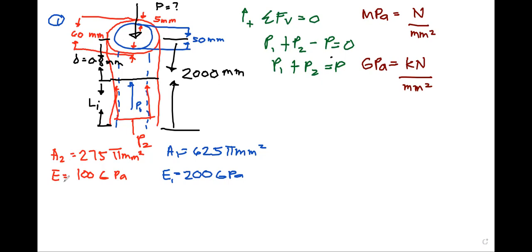So, we can say that deformation 1 is equal to deformation 2. And of course, if their deformations are equal, length 1 and length 2 should also be equal. Okay? So, that's it. If those are equal, we can now solve our forces.